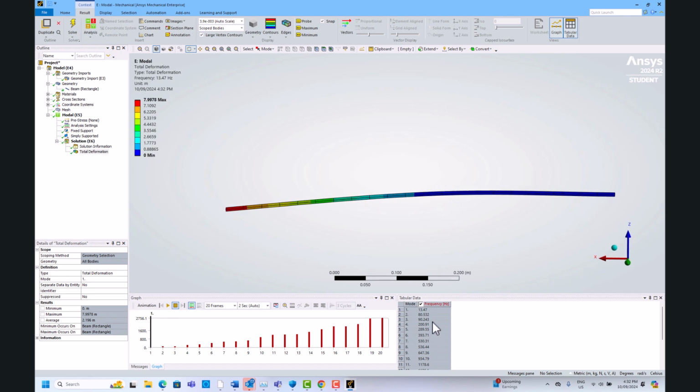So the first one, you can see this is a big table of all the natural frequencies that I mentioned. It's in Hertz, and the first one is our first mode, right? So remember what our experiment results were? It's about 13 point something, about 13.1. But our analytical solution gives us about 13.4. Okay? So anyone think about why we're getting a bit higher number than what we experimentally measured? Some possible reasons?